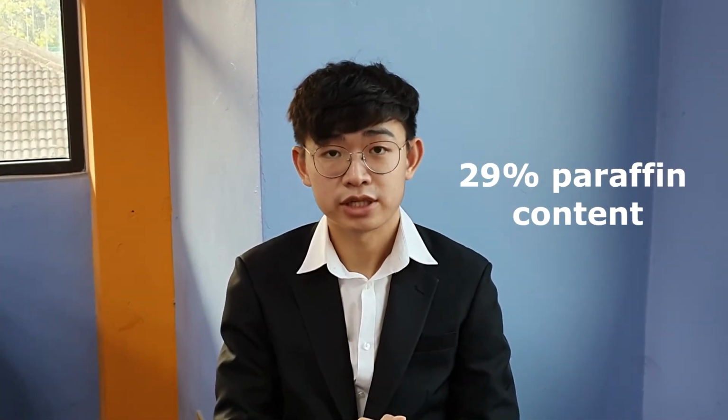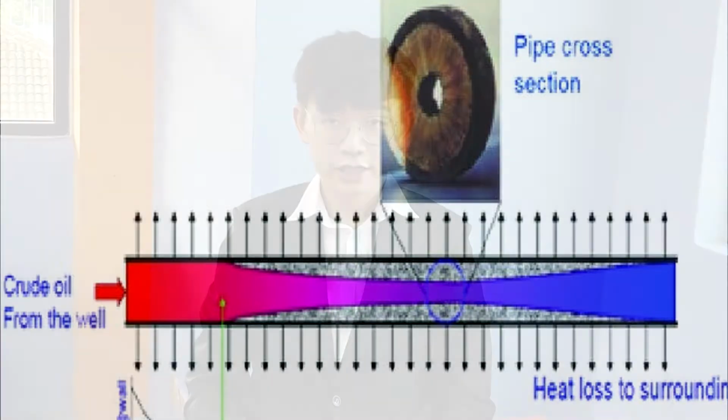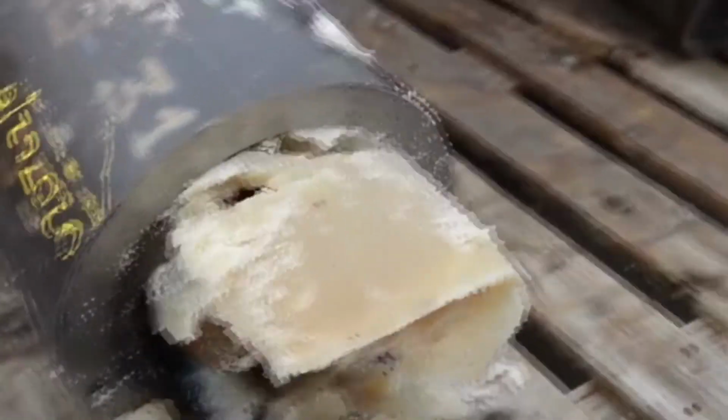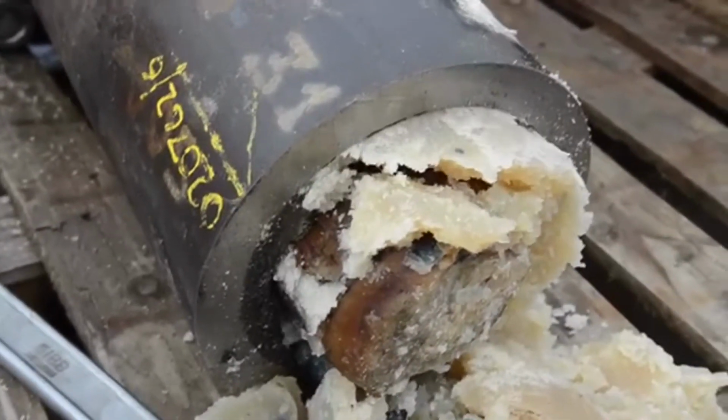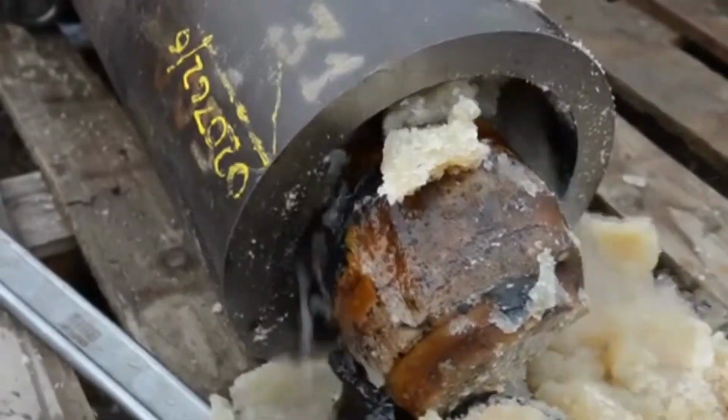Sample crudes from Bach Ho oil field show around 29% of paraffin content. This is considered high, and this high paraffin content will cause wax deposition on the pipeline. Wax deposition can lead to several technical issues, such as a reduction of diameter in the pipeline, reducing the operating capacity of the production system, or in extreme cases, blockage of the whole pipeline. All these technical issues can lead to financial loss to a company.